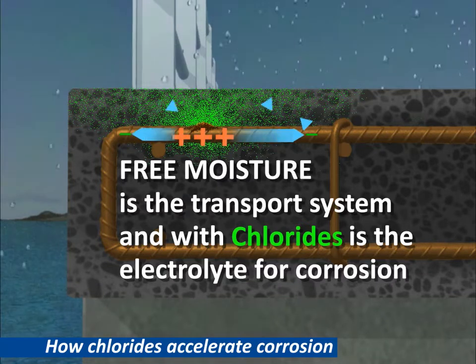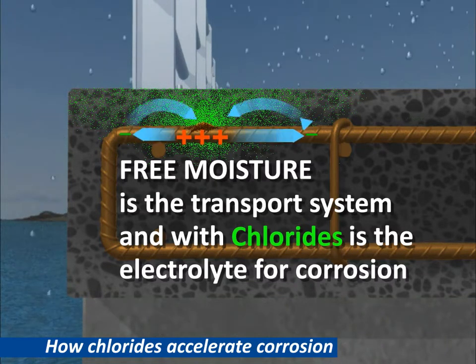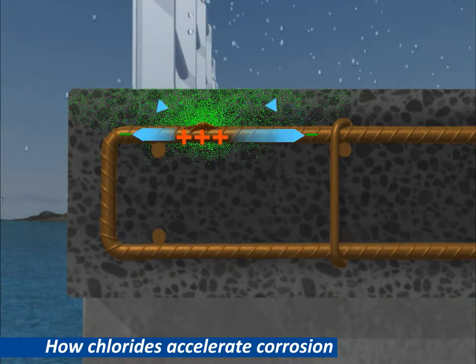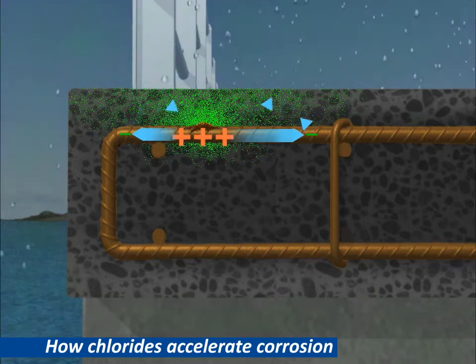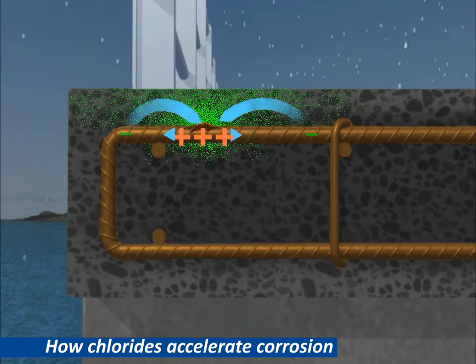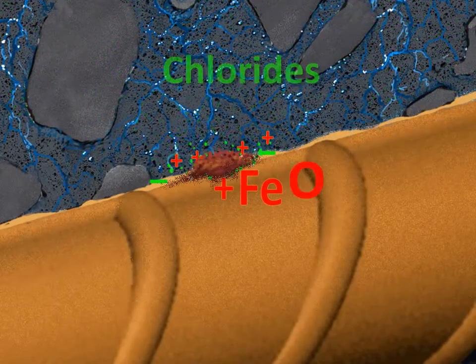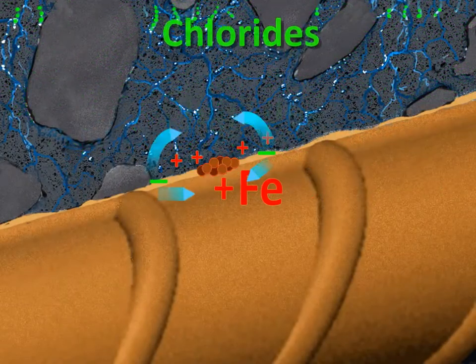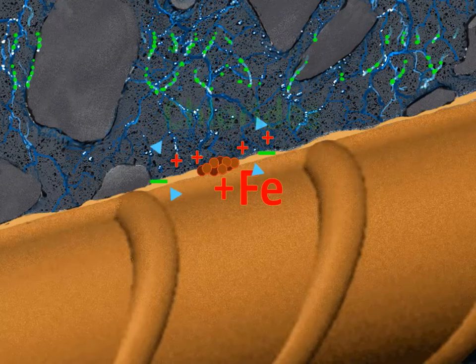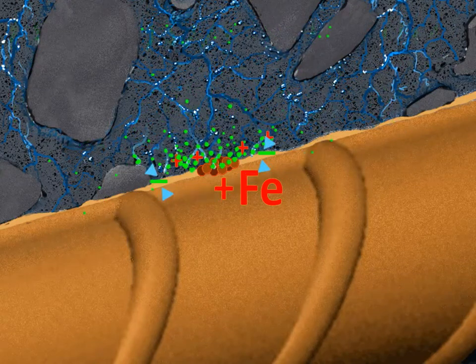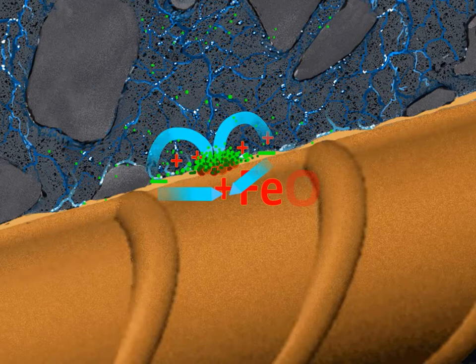You can see here the positive galvanic potential of the steel is attracting the negative chloride ions. Then the ion and electron flows start up and accelerate the corrosion. Once there is sufficient chloride levels at the corrosion site, the corrosion accelerates quickly.